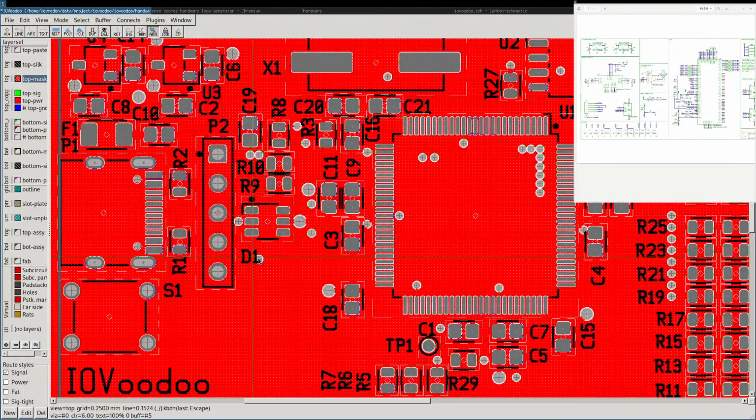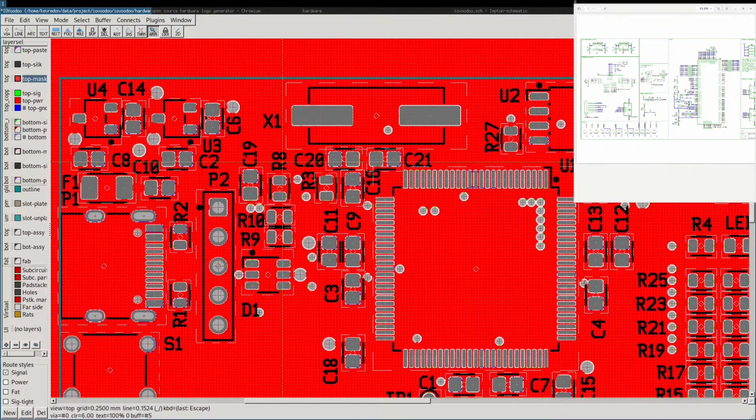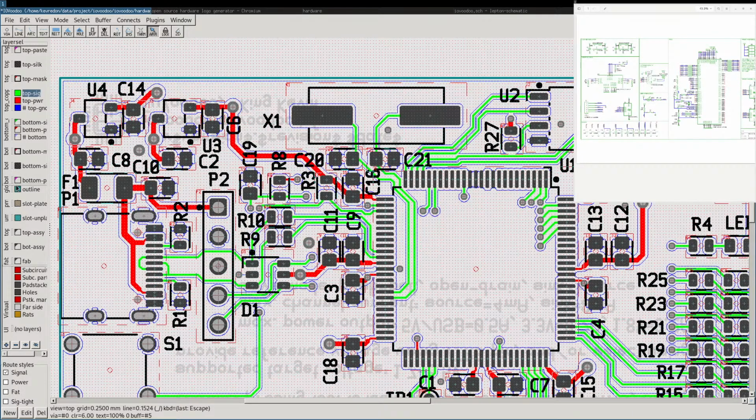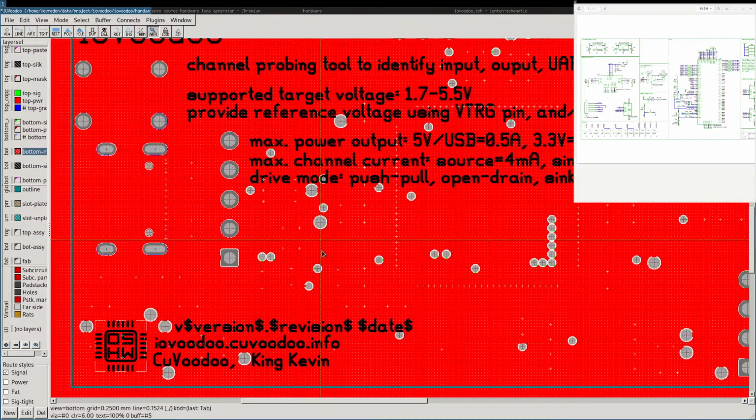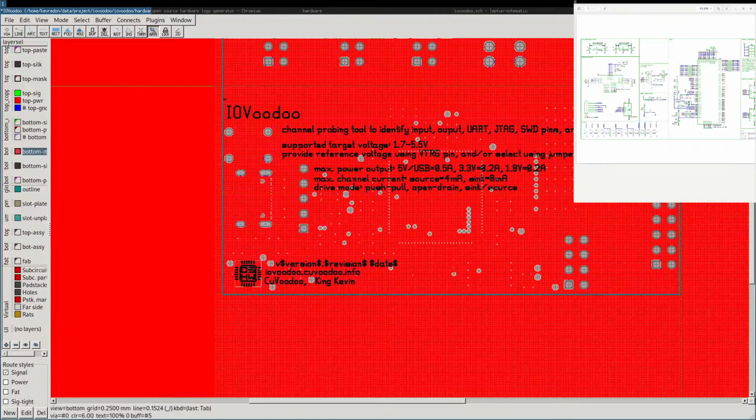And I could change the pad stack to have them tented. I don't want them tented. Let's see if they are able to do that or if they will complain. They meaning the fab house. I will select. So this looks nice, and we can check also the bottom mask. Let's switch the order. This is the bottom mask. It looks also nice. All the holes have solder opening.